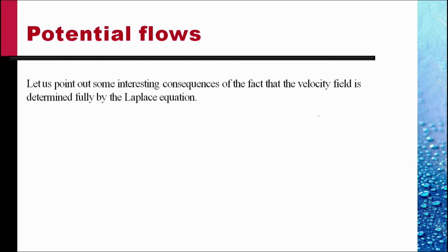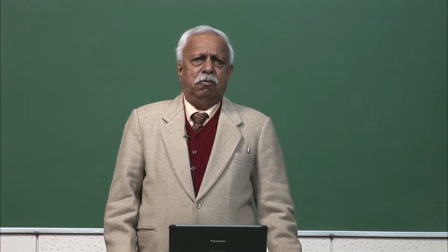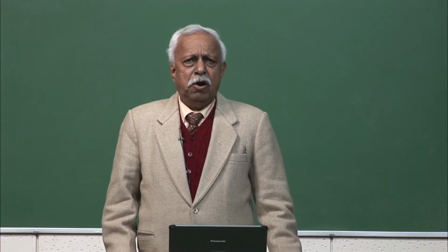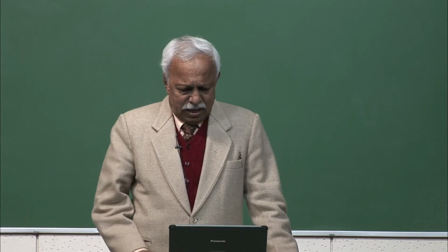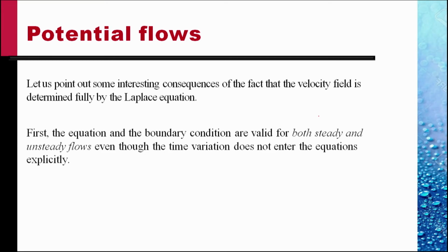Let us point out some interesting consequence of the fact that the velocity field of a potential flow is determined fully by the Laplace equation. First, the equation and boundary conditions are valid for both steady and unsteady flows, even though the time variation does not enter the equations explicitly.